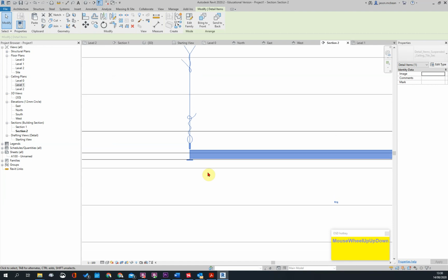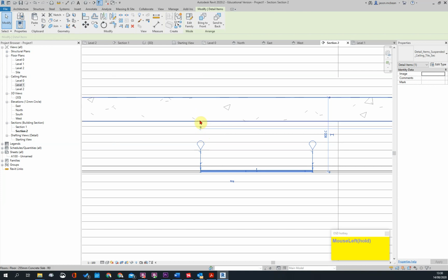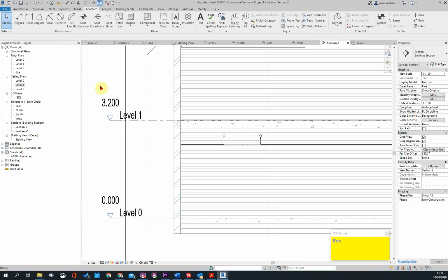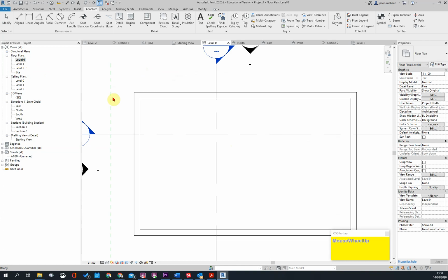That's where your ceiling board sits, and then these stretch up, so you just need to offset where these start, or you make a family that adjusts. But in essence, if you were going to build a bulkhead, for example, in Revit, that's very easy. So let me show you that very quickly. So say now your bulkhead would run around here, then your ceiling would stop.